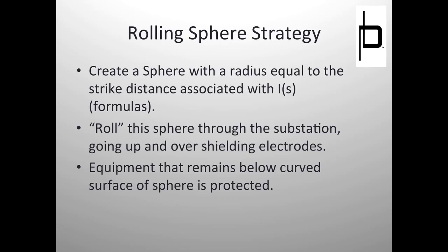Yes. Okay. So if it can reach a grounded electrode or a shield wire, then there's no need to roll through it because we know it can reach it, so we'll move on. So that's why we roll. You're going to tell us how to get the length of the step leader? Yes, that is going to be associated with our stroke current. Now, you'll ask me in a little bit what our stroke current is, and we'll get to that. But that's the strategy behind the rolling sphere.